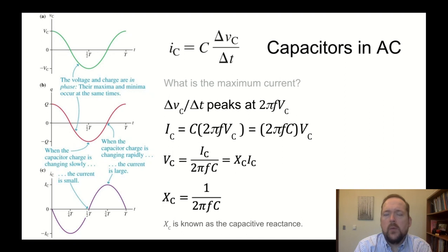You can think about it in the same way that you think about resistance, but whereas resistance is a steady amount of resistance to the flow in the circuit, capacitive reactance actually is a dynamic resistance to flow in the circuit, and it depends on the frequency at which we're switching the current directions in my AC circuit, as well as how much capacitance I have here. So if I have a really small frequency, that means I'm not changing current direction very quickly at all. I have a large capacitive reactance. That capacitor blocks current flow in the circuit quite well at low frequencies.